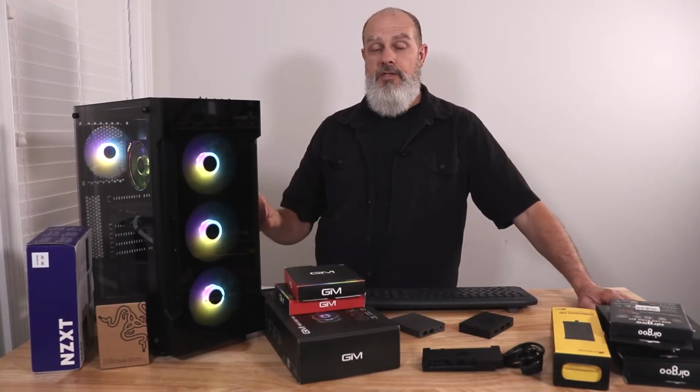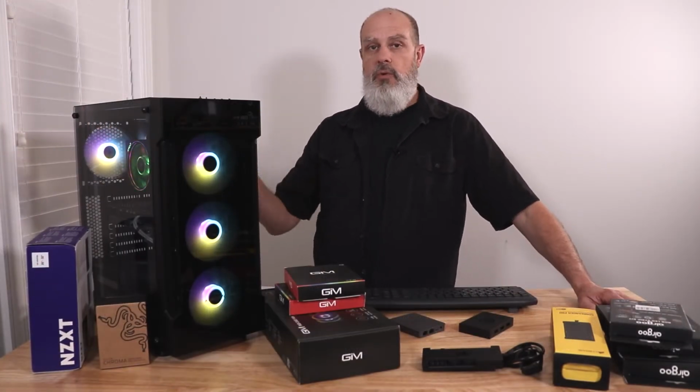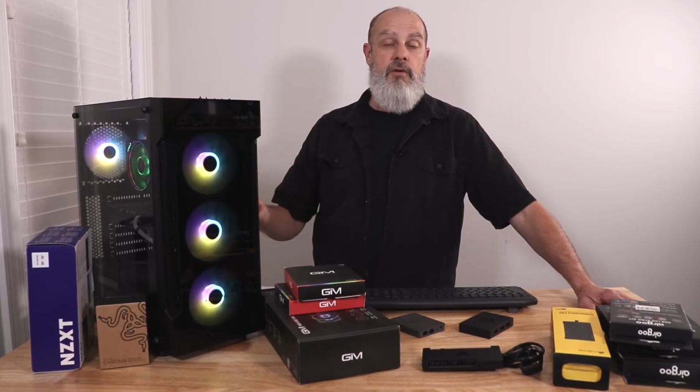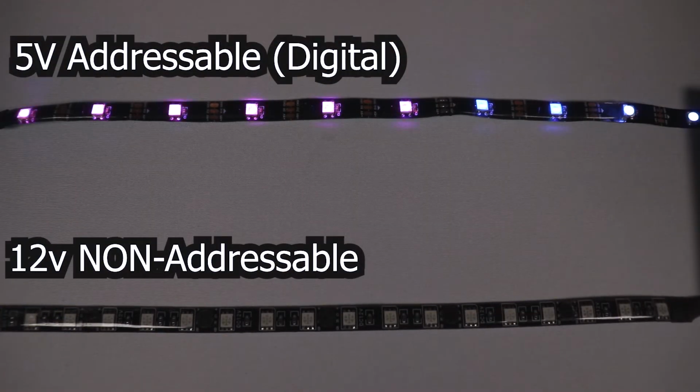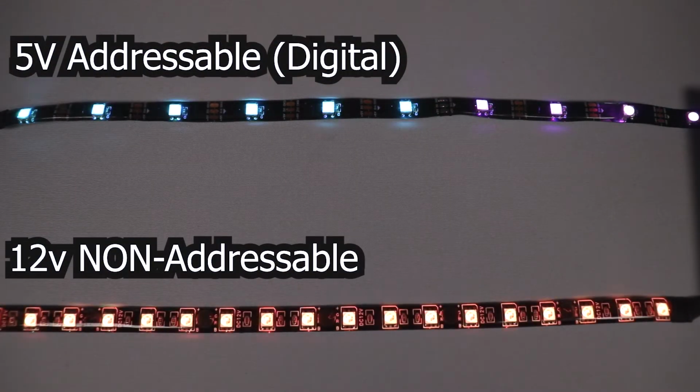That's going to be the fancier lighting that you see, all of the really cool lighting schemes and effects. Those are all going to be 5 volt ARGB, meaning that you can control each RGB LED individually by itself. You can turn each one a different color, and you can do all sorts of really cool stuff with it. The 12 volt connection is going to still be RGB LEDs, but you'll be able to just control the whole strip with the same color. So it can all be blue, it can all be red, but not at different times.